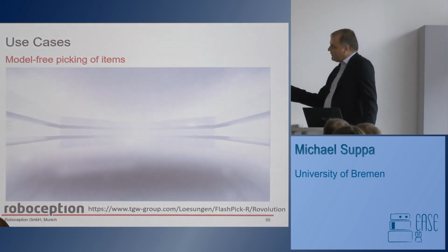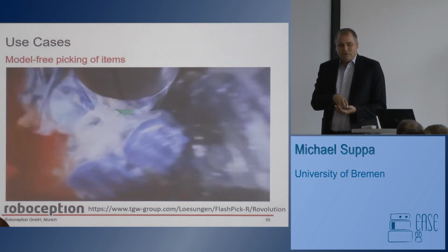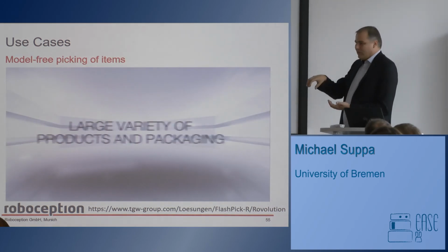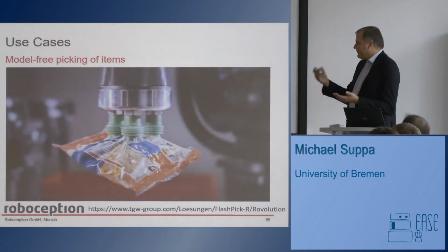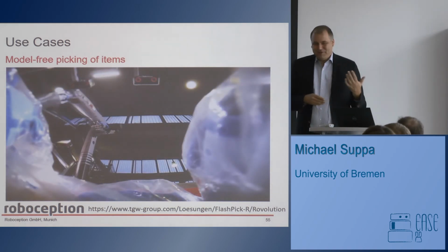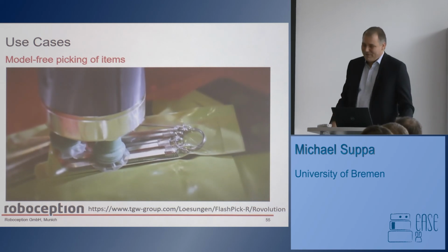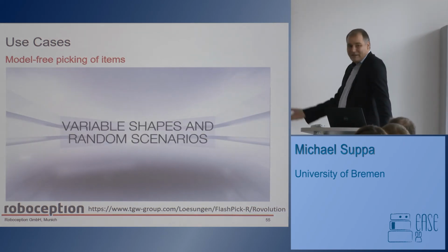They have a scale below the bin, because it's also important what happens if you don't grasp it. The suction cup knows it, but you also want to know if you grasped two or three, so they have scales below. For a vision guy, it's really stupid to say, okay, I need an additional scale. But for the 24/7 performance, it's okay to have it. It's not extra cost.